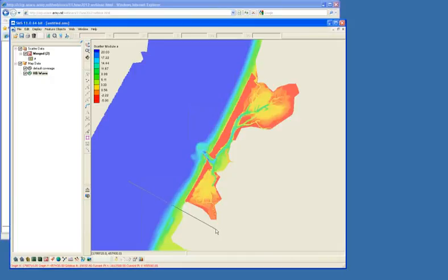So we build that, and I've missed a little bit of the bay, but that's no big deal. I can move this grid frame later on. So I've got the area now that I want to create the grid frame for, and I can actually extend that back to get more of an area. And so we can do something like this as our grid frame.